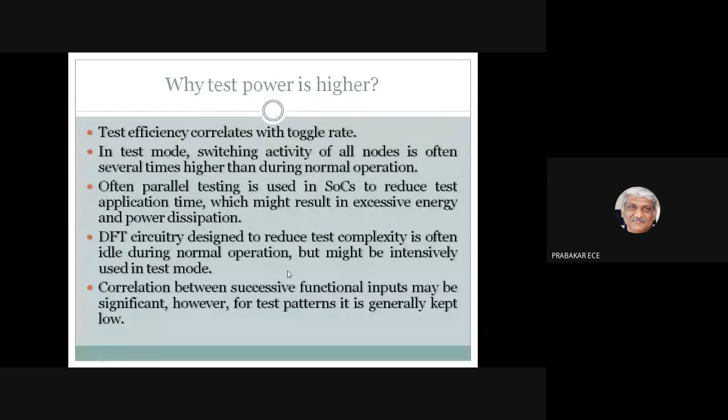What you can do is the design for testing. You will be adding some blocks in order to test the functionality of your FPGA. Now, that will be used only during the testing, and during the normal operation, this block will not be used at all. But you are going to waste some silicon area for your DFT, which will be causing some static power consumption, right? Because of this leakage power, there will always be some minimum power consumption because of these testing circuits. And these are all, of course, some issues why I am going to consume more power for testing.